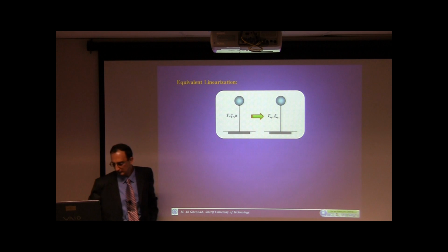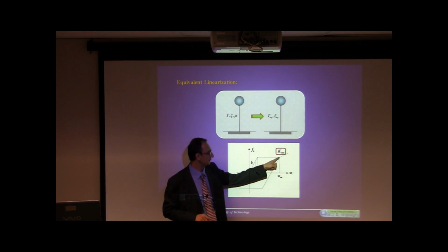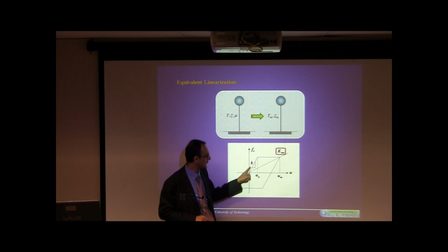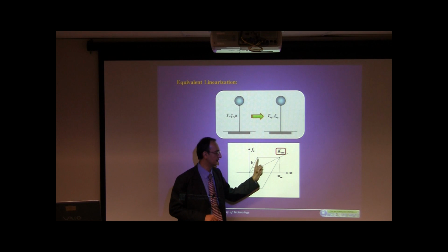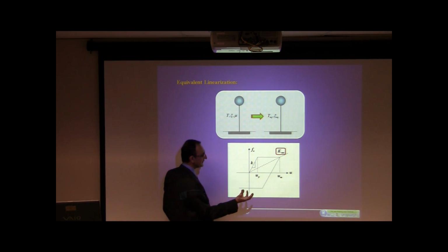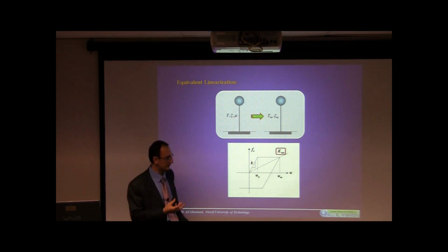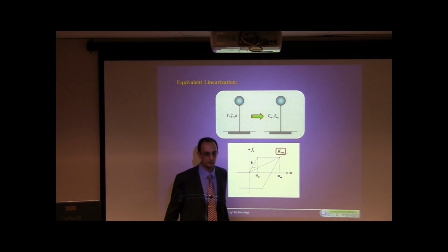And the first attempts used a secant stiffness, considering the maximum ductility and maximum displacement in the system. And then they associate the damping ratio with the period resulting from this secant stiffness to find the response of a structure.